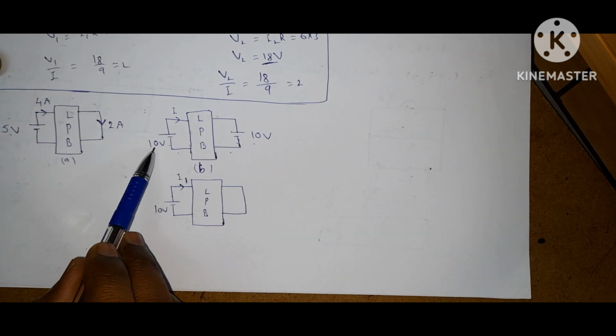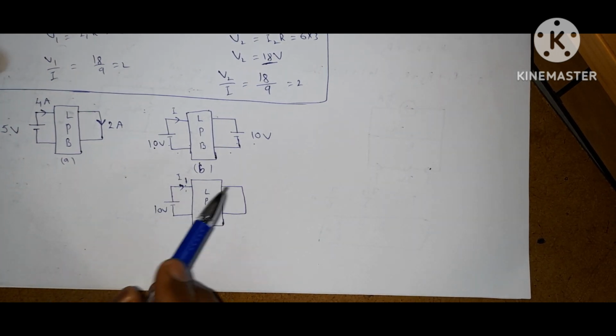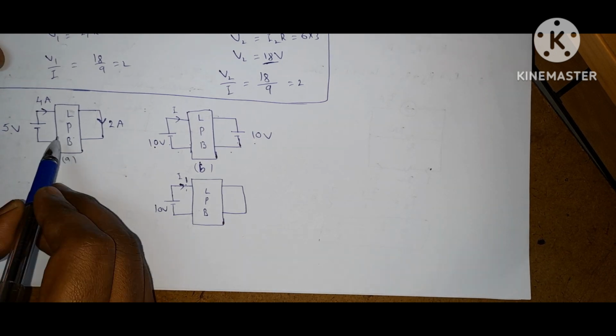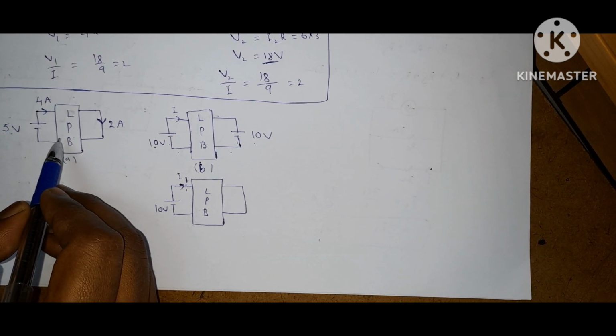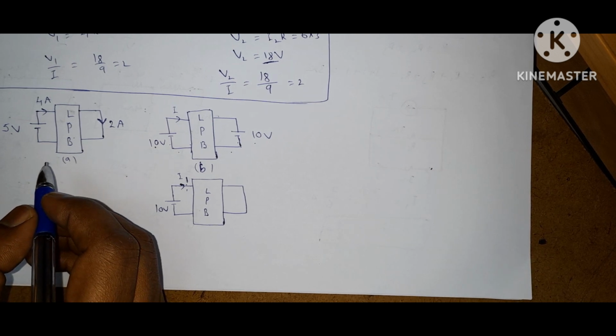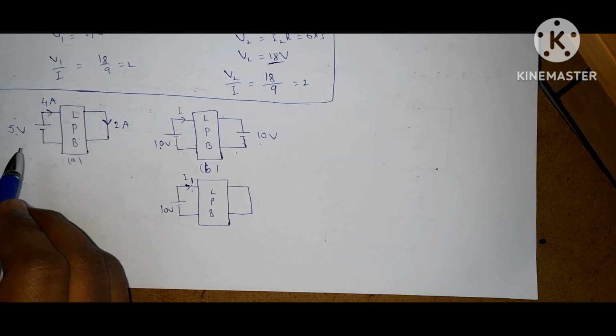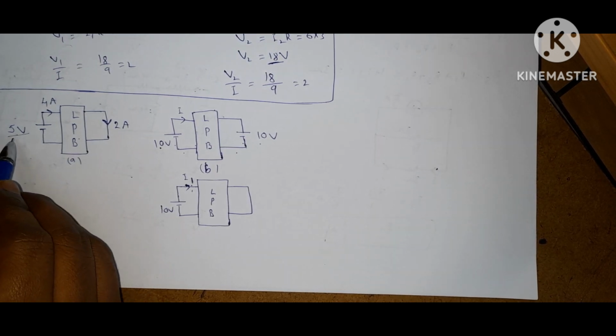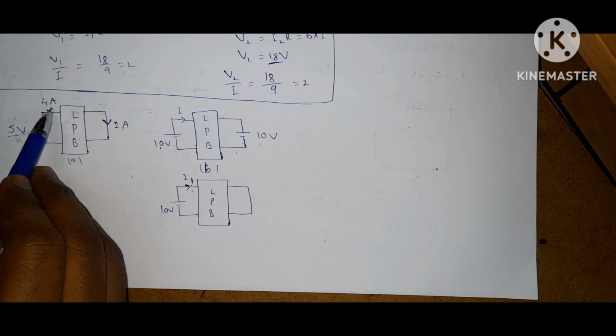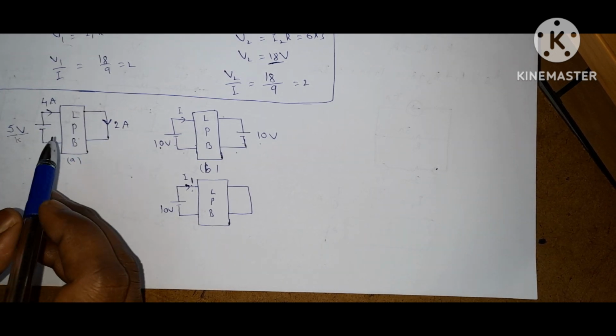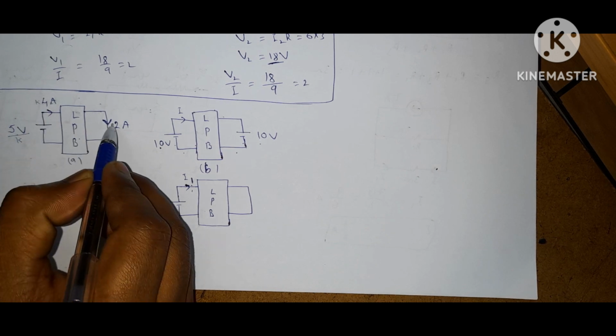Due to one source acting alone, the current is written as I1. Now coming to this circuit, by the homogeneity principle. What is the homogeneity principle? In previous lectures I have already discussed: if excitation is multiplied by some constant k, then all responses in the network are multiplied by the same constant k.